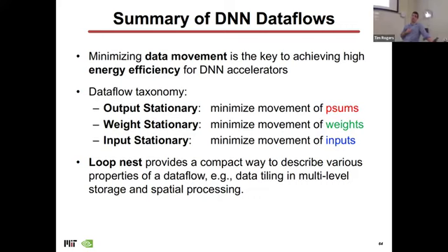And because the granularity of the computation is so large, I know before I start processing this layer what all its dimensions are. Why would I put complexity in the hardware to try to tile things if I can just tell the software to tile it appropriately? It's going to run for several minutes, and it's going to have the same access pattern over and over again. Then I'm going to train it over and over again on batches and batches of data. The pattern is so predictable that it makes a lot more sense to put it in software than in hardware. So I would hazard to say that by and large, most successful companies are punting a lot of this to the software and then trying to keep the hardware lean and mean.